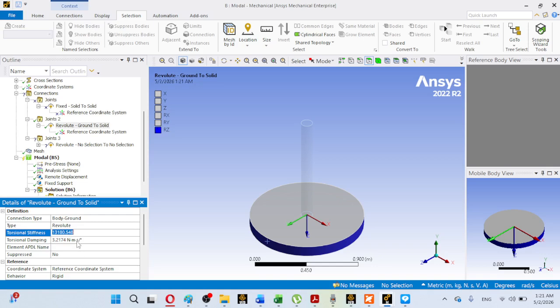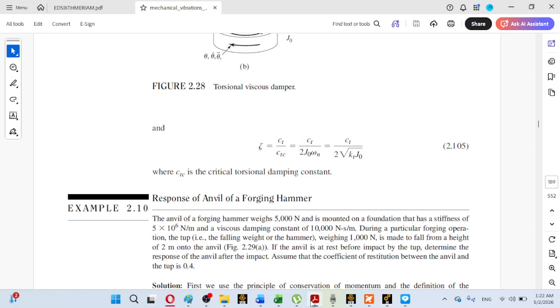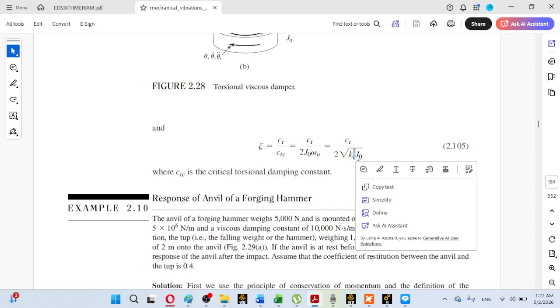After that, that is the torsional damping constant. So the torsional damping constant is calculated from here. Here you can assume the damping factor, torsional damping factor you can say, to be 0.3, and the critical damping constant, as you have now calculated kT already, that was 13180.548.